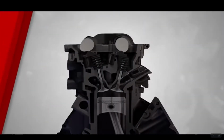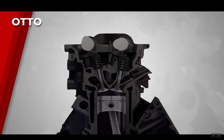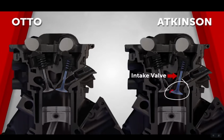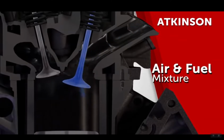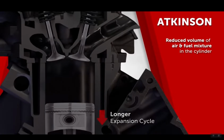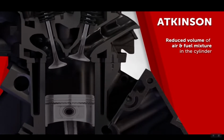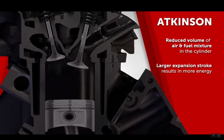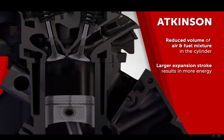In a traditional engine using the Otto cycle, the compression and expansion strokes are equal. However, the Atkinson cycle holds the engine's intake valves open longer. This results in some of the air-fuel mixture being forced back into the intake manifold. This delays the start of the compression cycle and reduces the volume of air-fuel mixture in the cylinder. As a result, the expansion stroke is larger than the compression stroke, which allows more energy to be extracted from the burnt fuel before exhausting it out the tailpipe.